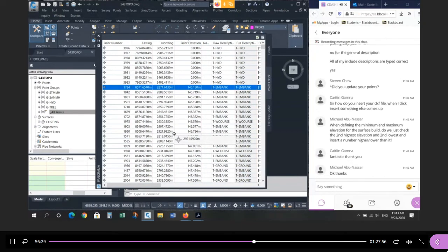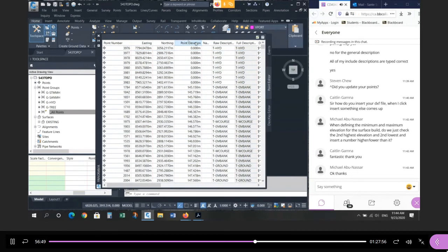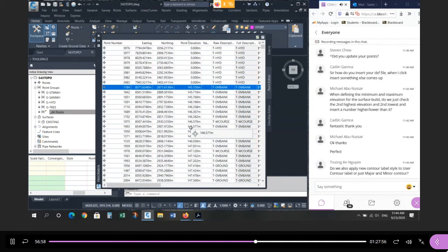So all numbers less than 100 will eliminate the zeros. And then if you sort it again, you'll see a bunch in a certain range, and then one of them will be way out. So then you pick a number just above this. Let's say in my case 200. Anything above 200, ignore it, and then it'll get rid of the high spike. So you have to sort the point elevation column to see what number you should use. And there's more than one solution, right? You just want to get rid of the spikes. So I can use, in my case, anything less than 100, anything less than 10, anything less than 2 meters. As long as the zeros are under that number, you're good. Okay.